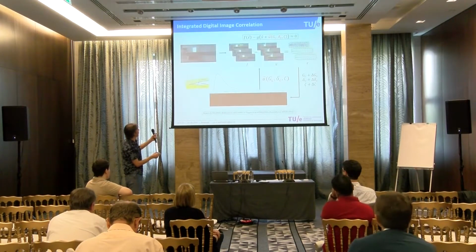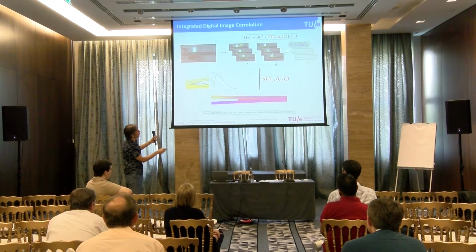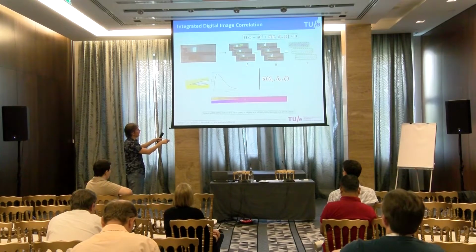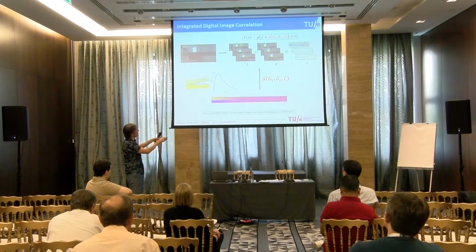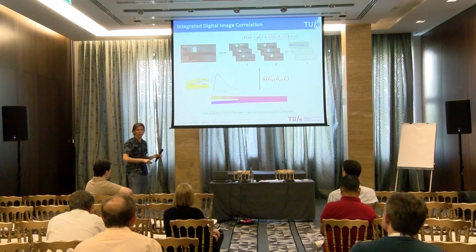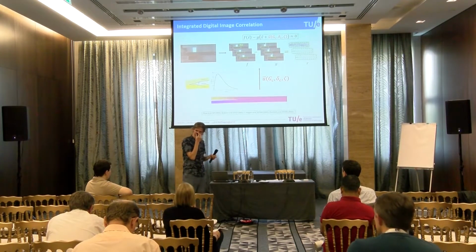So that's really on the modeling side. So here you can see it. These cohesive zone elements basically have 3 parameters. There's a formulation in there for how the traction and the opening go, but this also changes with the angle under which the interface is being loaded. This area increases with a factor of 3.5 when loaded in mode 2, instead of mode 1, if zeta is 3.5. Because GC will depend on the mode mixing.